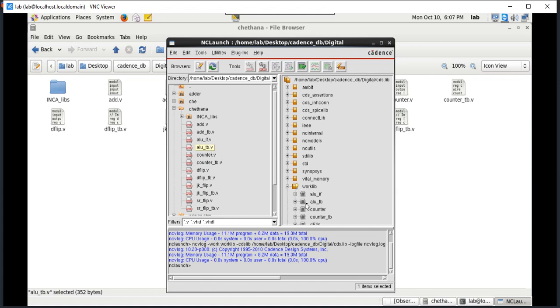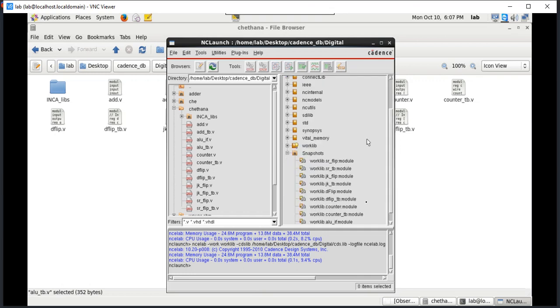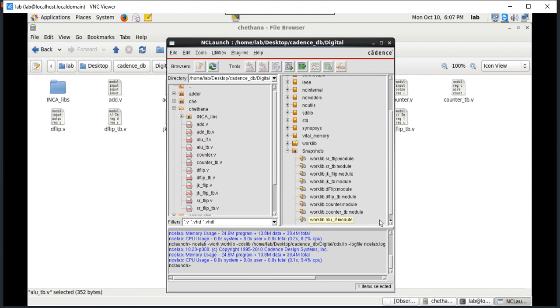This is the module name here. Now click on the module name. Then the next tool will be highlighted, which is elaboration. Click on that. Again, if there are any errors, they will be displayed here. Next, consider the test bench. Elaborate the test bench program also. No errors. Now you can proceed to snapshots. Snapshot, this is the ALU program and the test bench. Now select the test bench program and click on simulator.